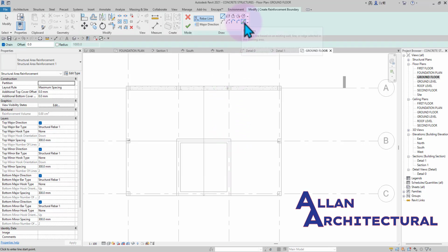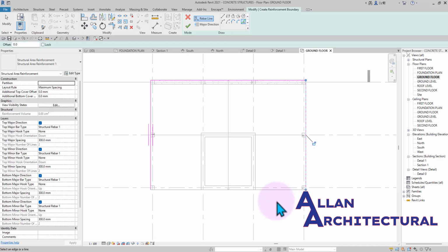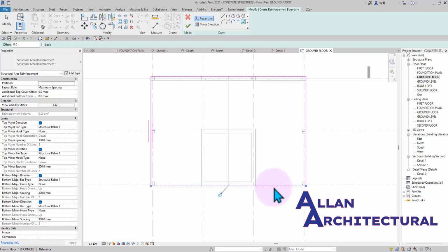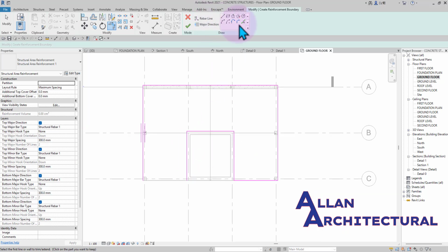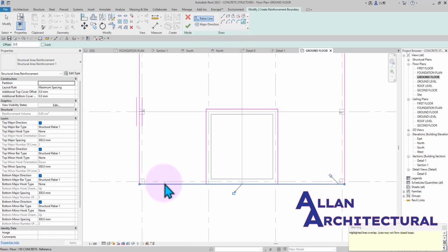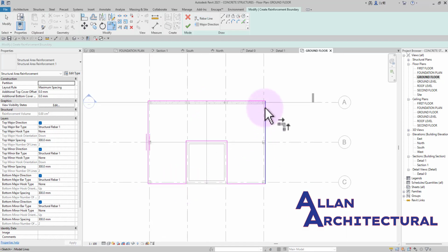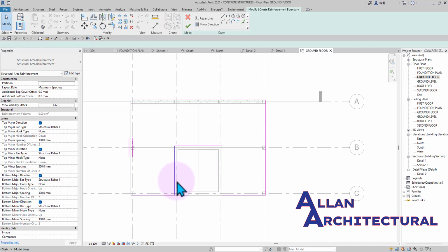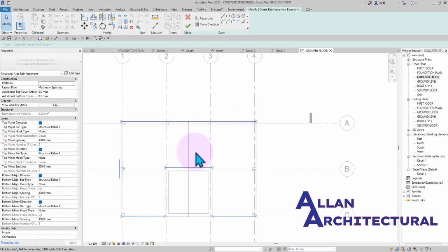So I'm going to start off by using the pick line tools. I'm going to pick this line, this line, and with this I'm going to pick it here, here, here, and here. So let me just trim and extend all of those edges, because this is going to be like a shaft, right? I don't want it going all the way in here. So I'm going to click one here and TR on my keyboard to trim all of this together. All right, so this is trimmed together, and you can select all of these. Let's make a broad selection.